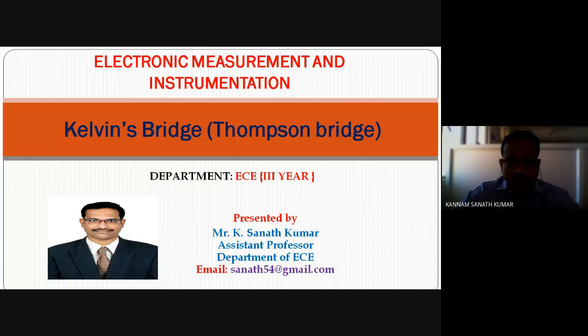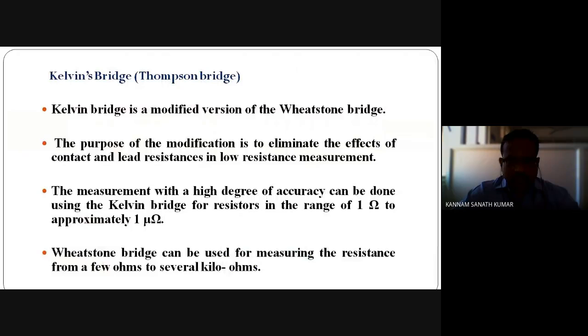Now today I will explain the Kelvin bridge, or Thomson's bridge. The Kelvin bridge is a modified version of the Wheatstone bridge. In order to find the lead resistance or contact resistance, which are very low resistances, we use the Kelvin bridge.